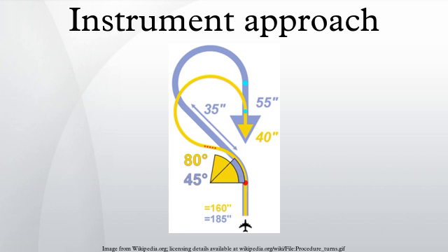Holding pattern, commonly referred to as the racetrack pattern. It is another method of course reversal, but it can also be used for losing altitude within protected airspace. A holding pattern used for this purpose is depicted in U.S. government publications as the hold-in-lieu-of-PT holding pattern symbol. The procedure has two parallel legs, with 180-degree turns between them.